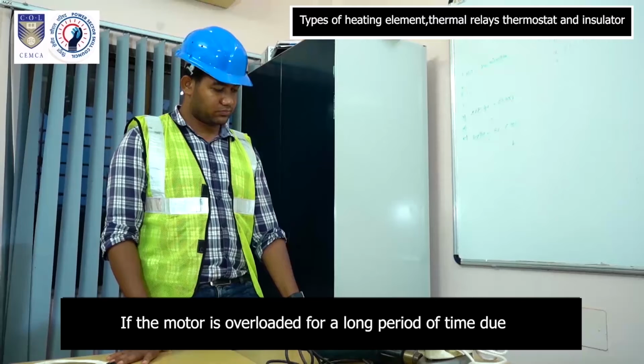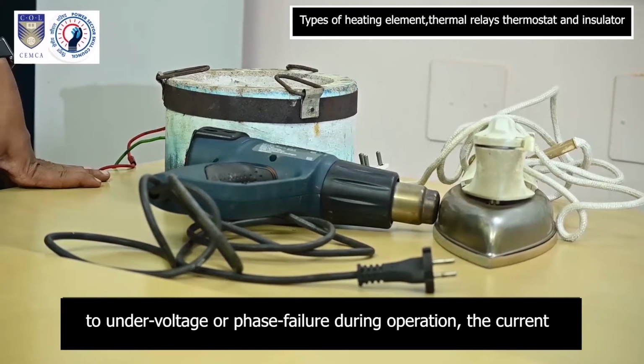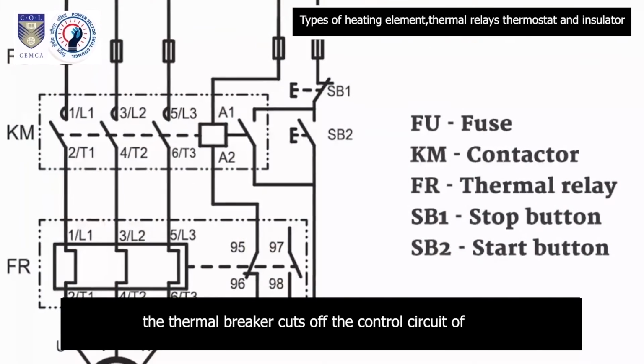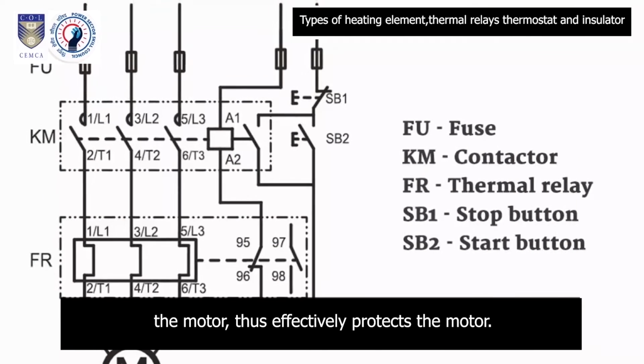If the motor is overloaded for a longer period of time due to undervoltage or phase failure during operation, the current of the motor will exceed the rated value. At this time, the thermal relay cuts off the control circuit of the motor, thus effectively protecting the motor.